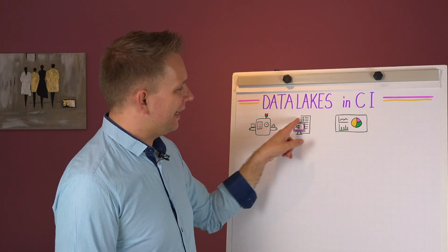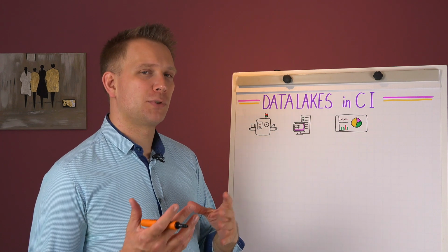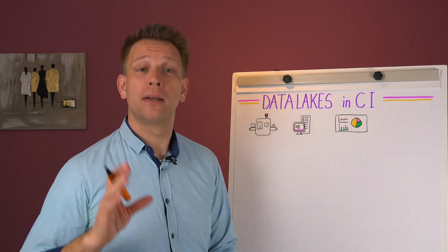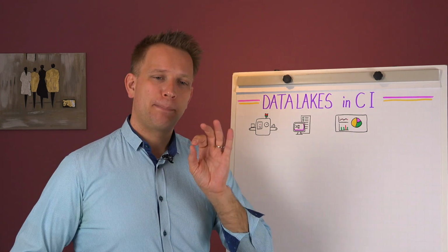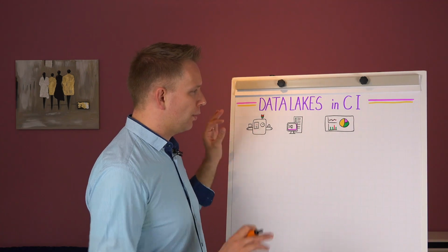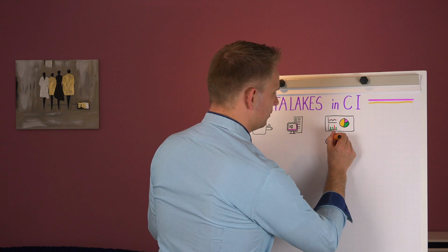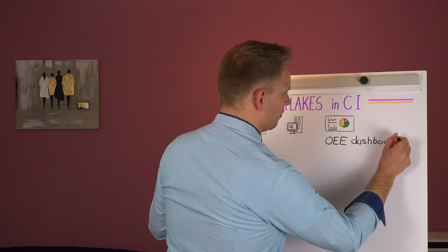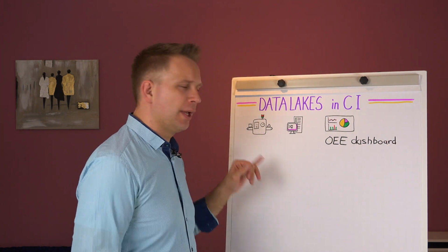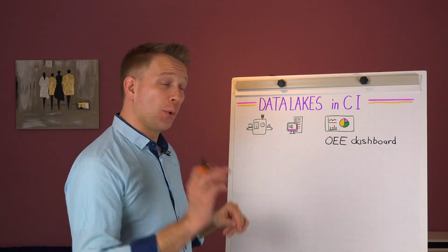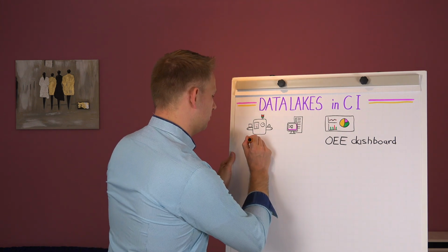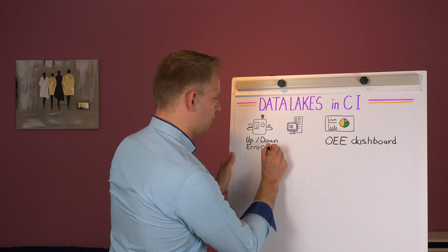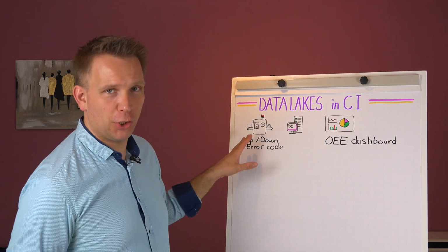That engineer will be setting up a data model, maybe buying one straight off the shelf from a specialized OEE data modeling and reporting company, lots of them out there, and it picks up all kinds of signals from the line. So if we want that OEE dashboard, what we need to know is all kinds of uptime and downtime things. We generally get that from the line: uptimes, error codes, things like that.